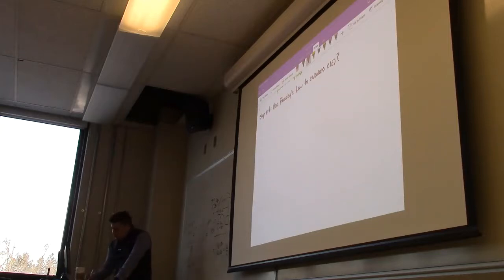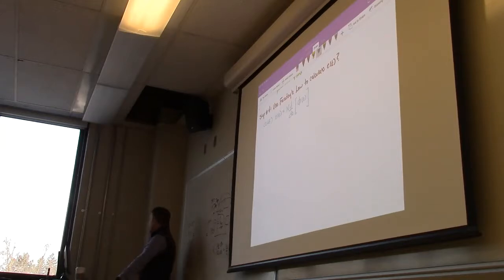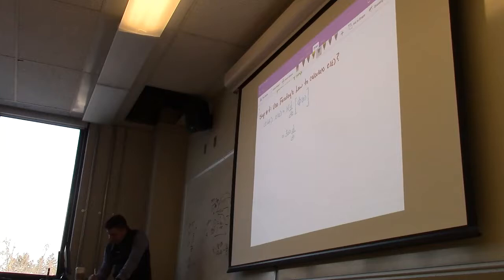And so this is equation 2.65 from the text. And it tells us that e of t is equal to N, number of turns, times the derivative with respect to time of our flux. And so now we can plug in essentially everything we know. We know the number of turns is 300. We can take the derivative of our value here.